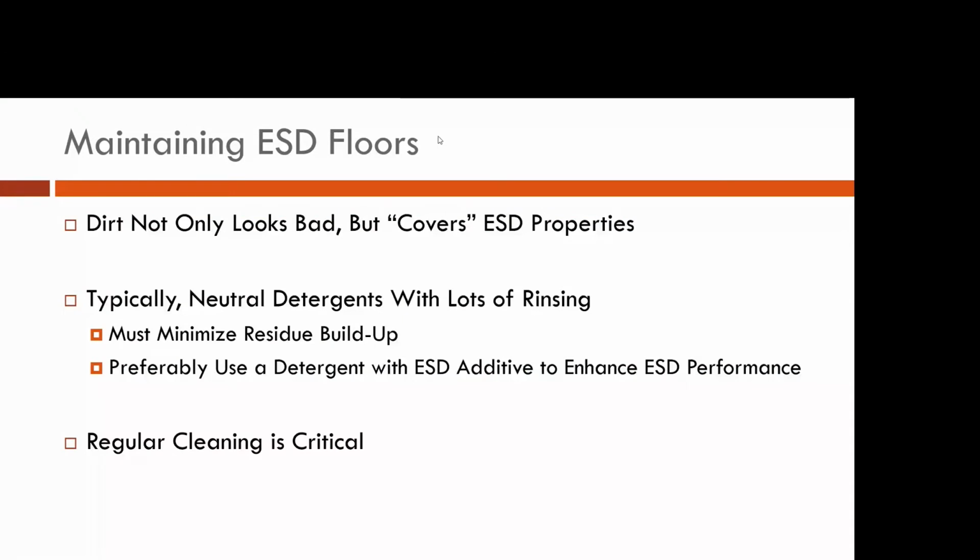The majority of ESD floors that we see fail aren't because the flooring material itself isn't working. It is because it was either improperly installed, there's issues with it coming up with water coming up out of the subfloor and causing failures, but also because there's a layer of dirt and debris that is built up on the floor and it starts acting like an insulative barrier.